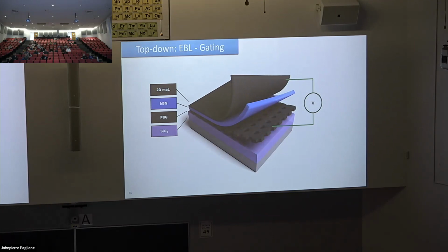So you're not removing atoms, but you want to change the dielectric environment. Maybe you want to pattern your backgate. This is similar to some of Jim's slides, where there's graphite on top, graphite underneath. But here the graphite close to the graphene has a pattern, a structure to it. So when you apply potential between the two, you are imprinting a potential onto the graphene that matches the shape of your patterned graphite. In principle, you can also pattern your BN spacer. That will also change how much electric field reaches the graphene.